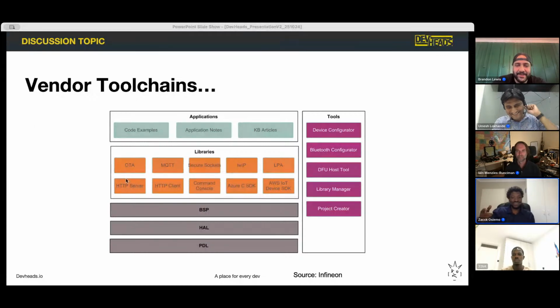Like ST gives you UART drivers, and then you're stuck for 2 weeks with a UART problem, and it's ST's code, and you could have bit banged it and it would have fixed it. This thing keeps happening over and over again, leading me down this path. And I suspect Marvin is the same because he builds compilers for fun. I don't know why. You want to know the thing for yourself so you can use it when you want, as you want. In the beginning it won't be as fast, but at some point the gains will get so big that you're moving faster than others, even though it looks like you're doing it the hard way. It's just because your driver could be 500 lines or it could be 10 lines.